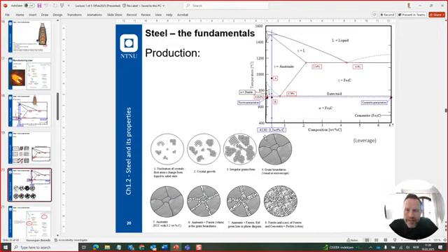If we see a different composition of steel, say that you have 1% or even 2%, somewhere in between there, of carbon inside your steel, you would actually have a combination of austenite and liquid. But with our composition, we are here, whereas the same temperature would still be at stage picture 3.